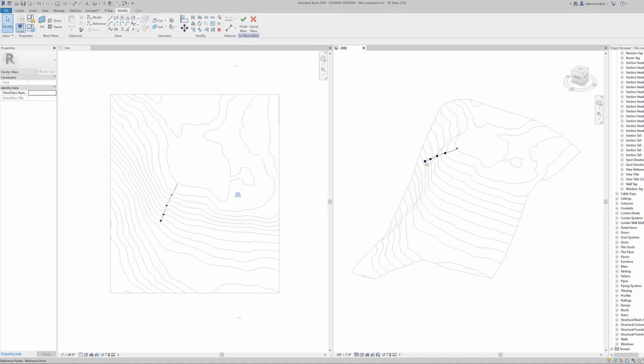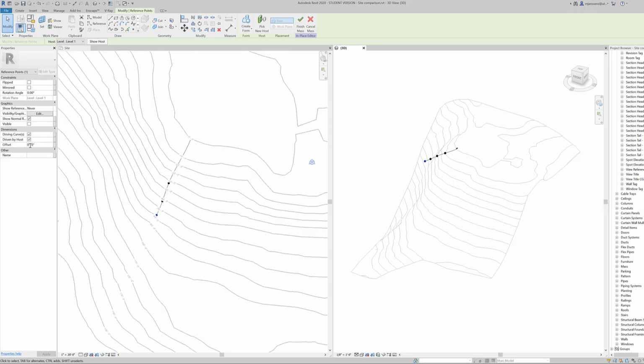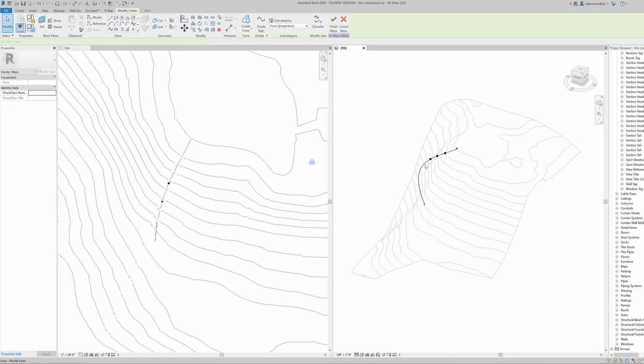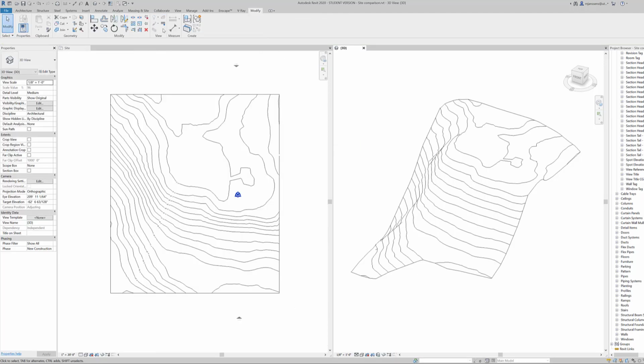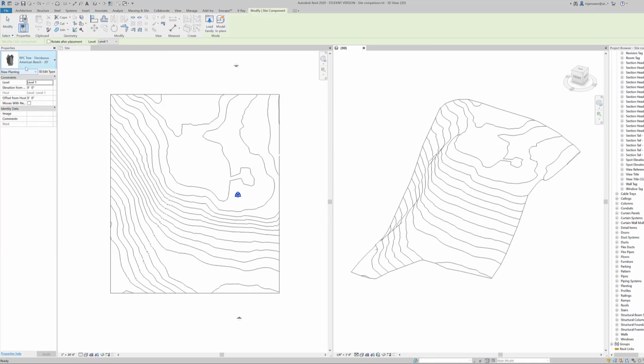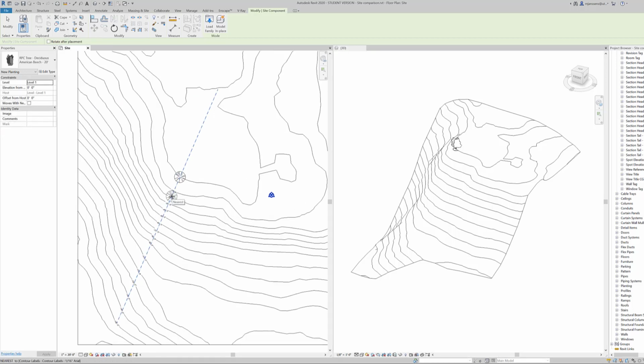But by drawing on the work plane, now we can give it an offset because we're giving it a datum. And I know that this one will be -80 feet. And so you can manually adjust each of the nodes on the line. But there is a bit of a workaround where if we use RPCs or site elements, which are designed to snap to the topo surface, we can use the geometries that they host or are hosted to actually give us an ability to snap to the topo surface.